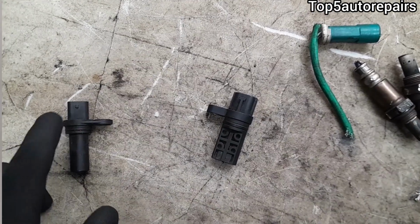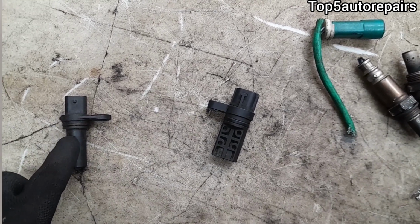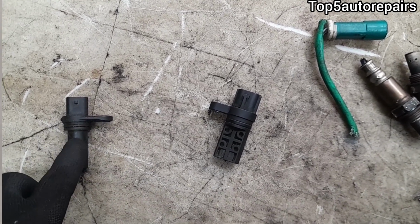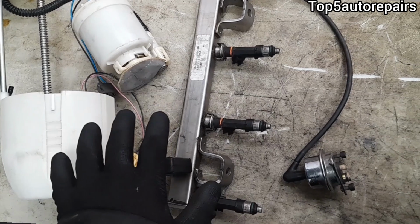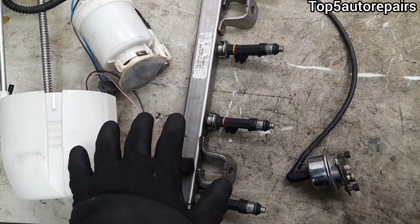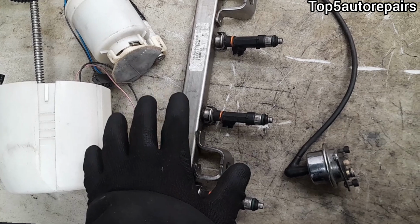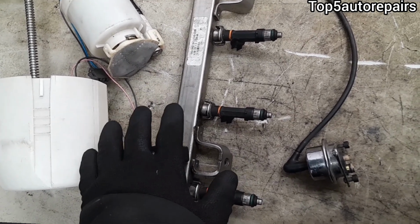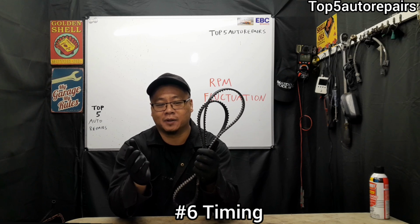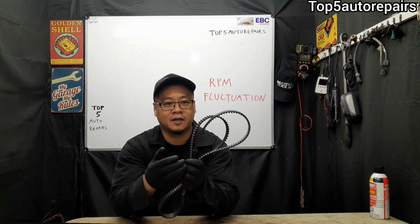The next problem is going to be a bad crankshaft sensor. If your crankshaft sensor is bad, you're going to experience rough idle, and also you're going to experience stalling and no start. The next problem is going to be a fuel system issue. If you have low fuel pressure or you have a fuel delivery issue, of course this is going to affect idle because not enough fuel is going to get delivered to the engine, and it's definitely going to affect engine performance. And lastly, timing. If your timing is off by a tooth or more, this can definitely affect idle.